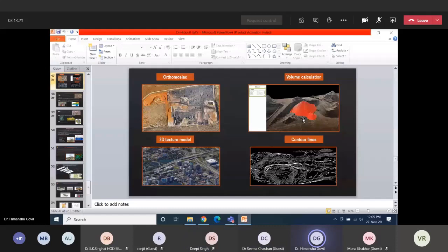For this, you will have to go for microwave remote sensing. If you have microwave cameras or microwave sensors, you can install them on the drone technology and get the area. But microwave remote sensing also has limitations in terms of the material. Like the L band can penetrate up to 4 meters in the case of loose sediments like sand or clay. But if it is a hard rock terrain, you cannot go under this.